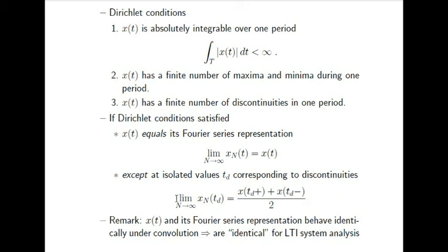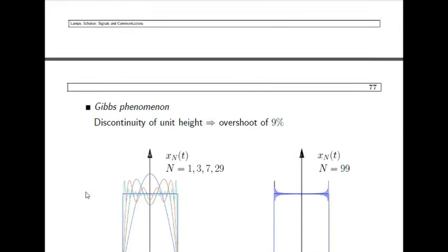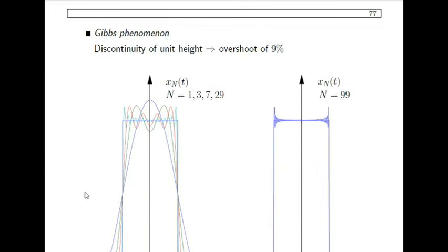The last topic which I am going to teach you in this tutorial is the Gibbs phenomenon. The Gibbs phenomenon is something used for approximation. I want to tell you that a square wave cannot be generated ideally. What is actually a square wave? A square wave is a summation of a large number of sinusoids. When we sum a large number of sinusoids, they compress together and form a structure like square waves or rectangular waves. But we cannot generate an ideal rectangular wave with sharp edges.